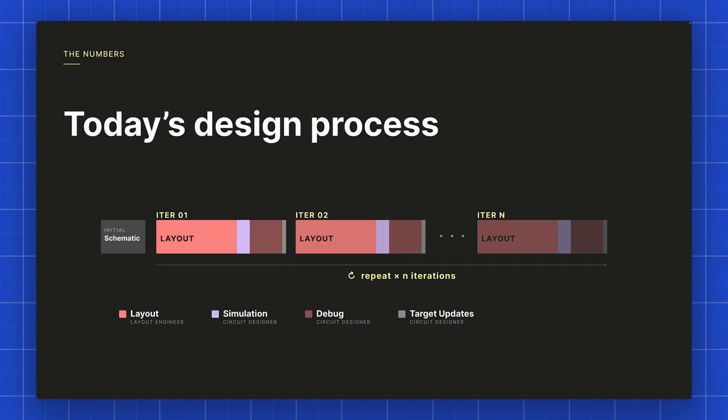How can our system improve the overall analog design process? In a logic node, a high-performance analog subblock takes many layout iterations to finalize and sign off for tape-out. The well-known loop is to produce a layout, extract, simulate it, then debug the problems and come up with targeted layout updates to fix these problems. Common problems include violations of electromigration limits and not meeting performance or matching targets. Large changes, especially after the initial layouts, are risky, so instead a process of repeated, limited scope improvements is used to lower incremental risk. Although this approach increases the chances of convergence, it adds significant overall delay.